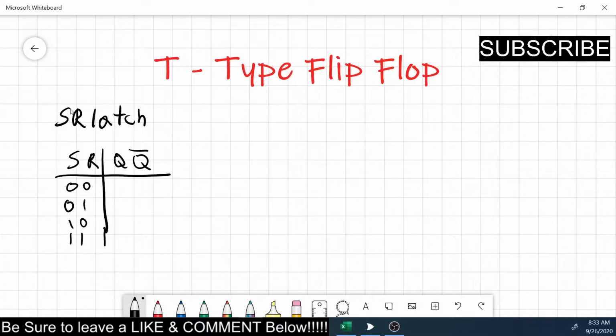So there's all your outputs. On your SR latch, if it was 0,0, it would be last state on both outputs. If the reset was done, it would be a 0 on Q and a 1 on Q naught. And if the set was pressed, Q naught would be a 0 and Q would be a 1. But the problem was when you did a 1,1, you got an invalid state.